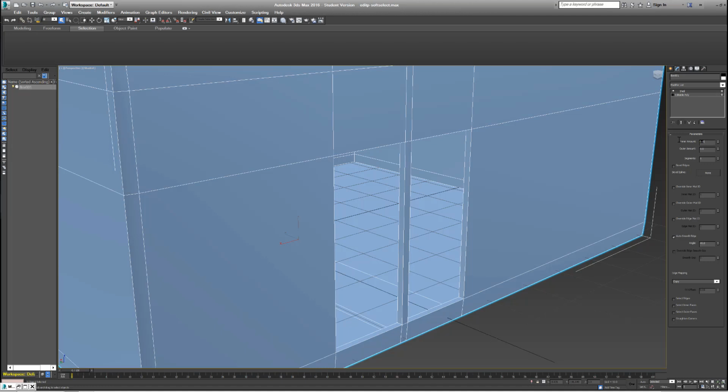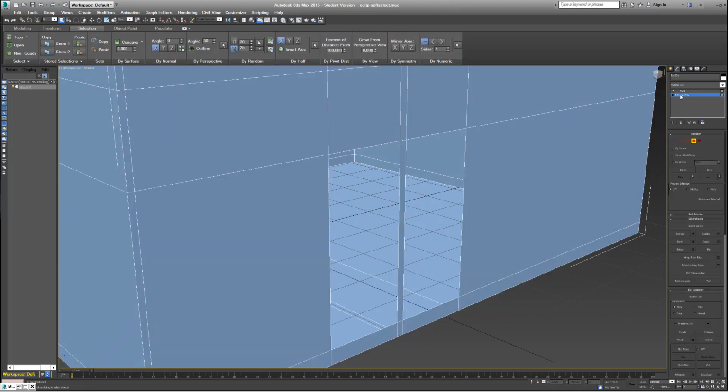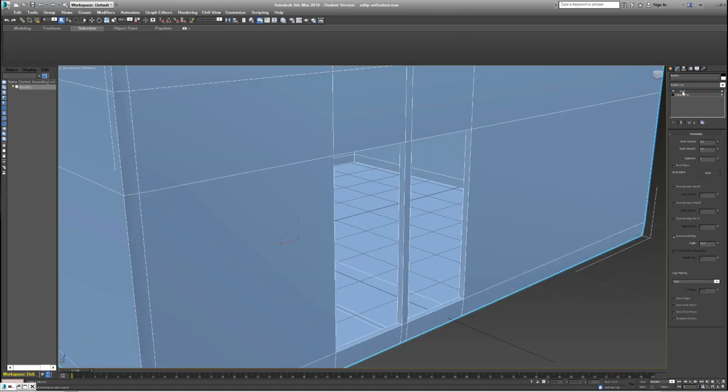Totally cool. You can bevel the edges. Otherwise, for now, these are for material mapping. I would not worry about this for now. Just the simple amount is inner amount, outer amount, or if you want the edges beveled, and that's going to affect your light quality. So this is good for now. If I ever want to get back into the sub-object level, I just simply click Editable Poly, and it gets back to that. So I've got my shell, and there you have it.